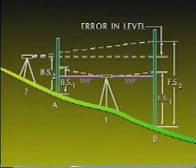Another back sight reading, BS2, is taken on the rod at point A, the point nearest the level. This gives a new elevation for the instrument height at setup point 2. Another fore sight reading, FS2, is then taken on the rod at point B. This fore sight rod reading establishes a new elevation for point B. We now have 2 elevations for the same point.